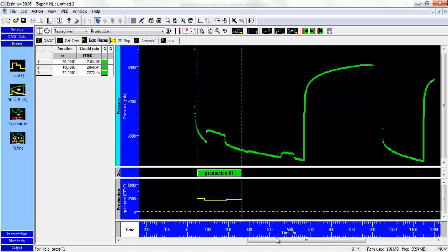Okay, so that's the most difficult job now. We need to estimate the rate data for this history here, and you can use different methods to do that. At this point, this is a new production well, so we still don't have the allocation system for this well. Based on your IPR and tubing performance, you can assume some rate. You can use productivity index as a method to calculate the rate. You can use a choke model, etc.